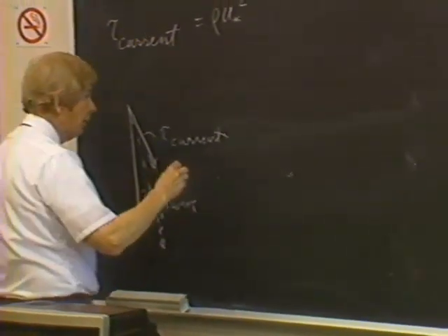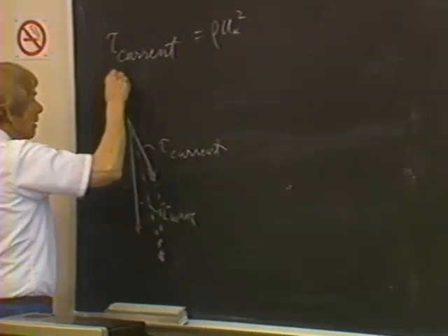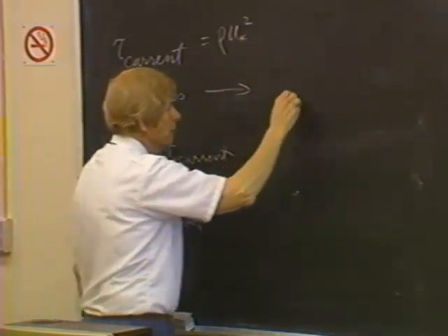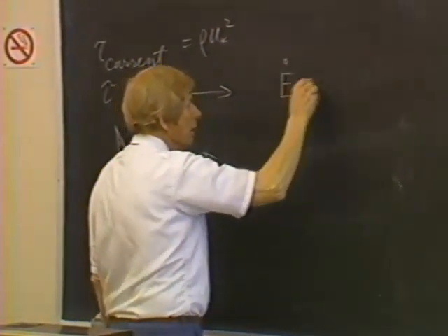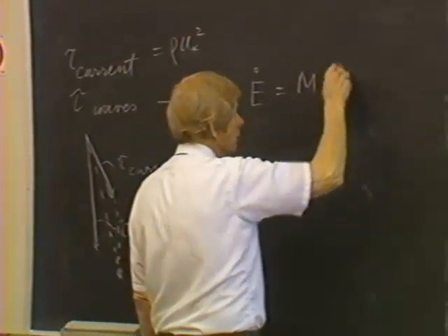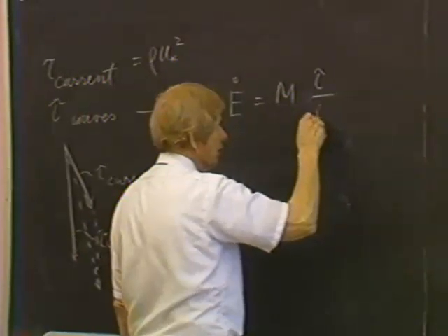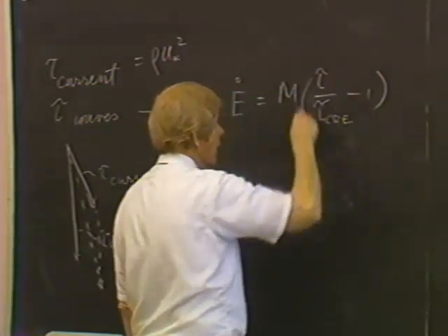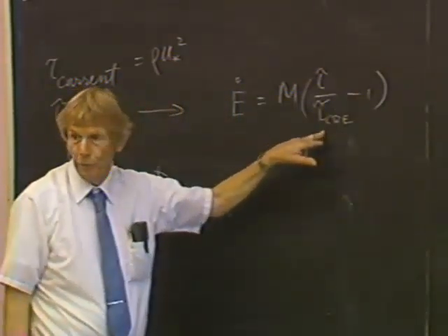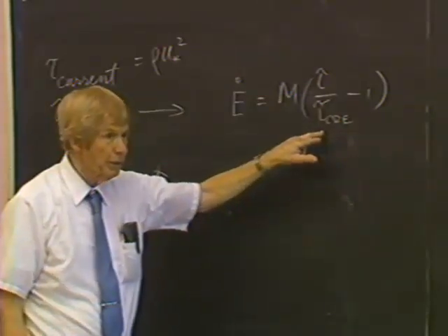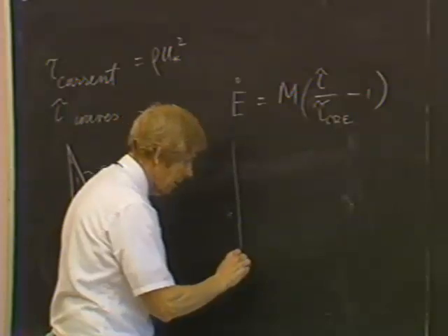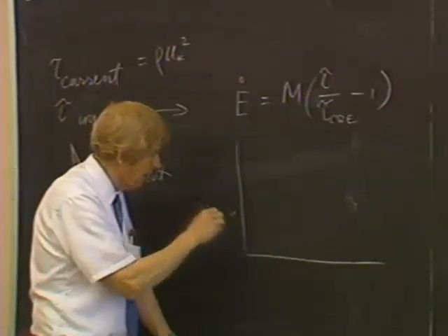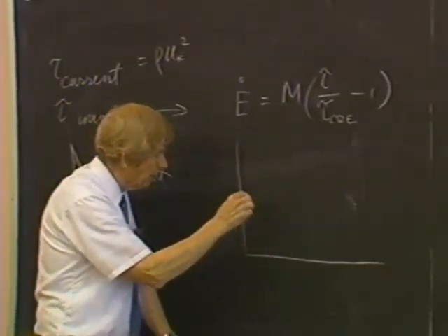There's one other thing about suspension by waves. Well, first of all, if you know the shear stress due to waves, then presumably you can apply that to the rate of erosion, which is equal to the shear stress divided by a critical shear stress for erosion, provided that you know the critical shear stress for erosion. And remember that changes with depth. In the flume studies report, it shows penetrometer measurements